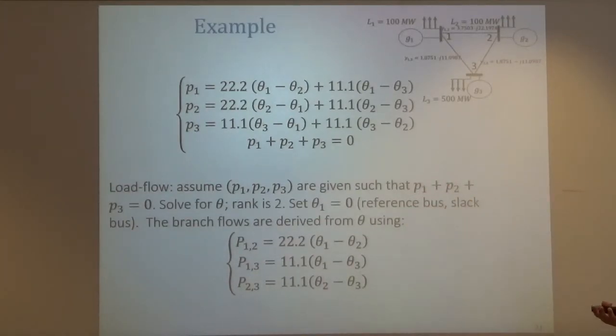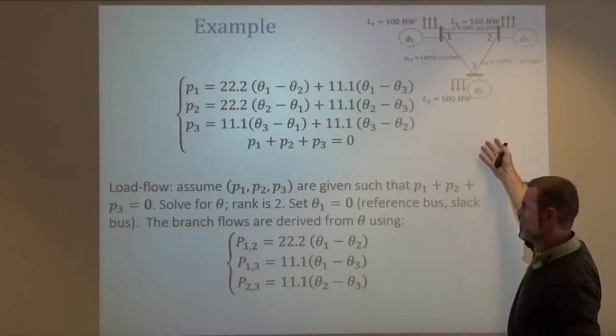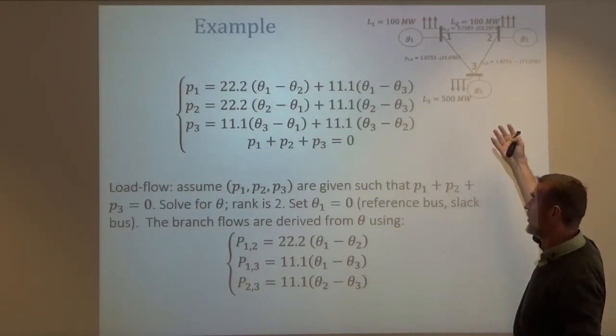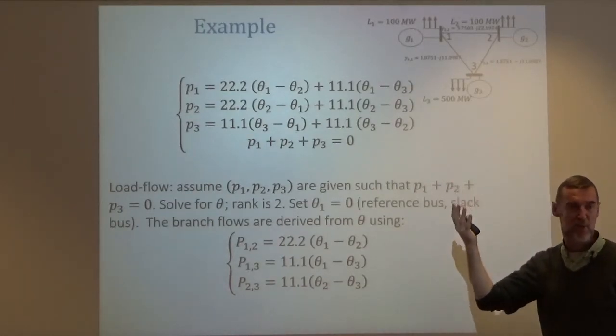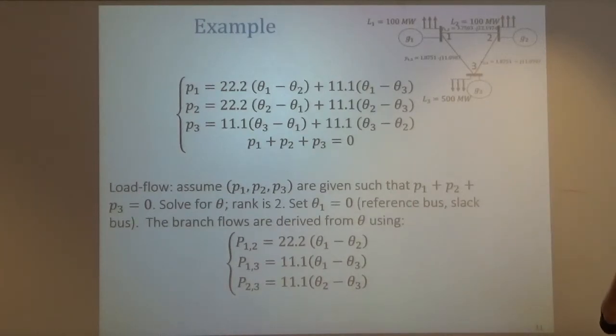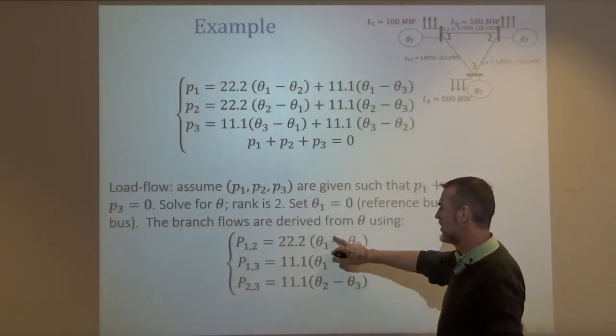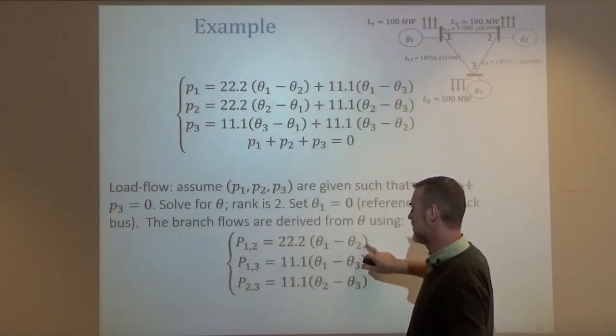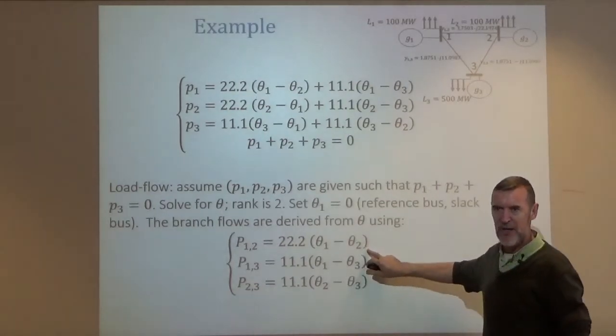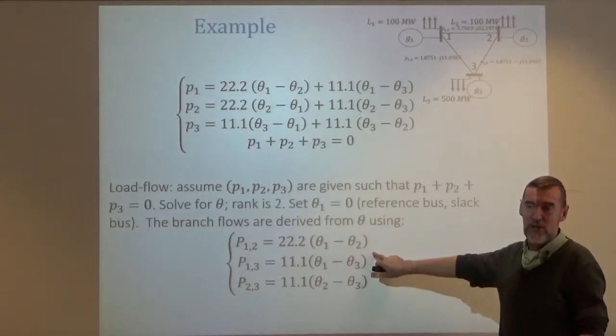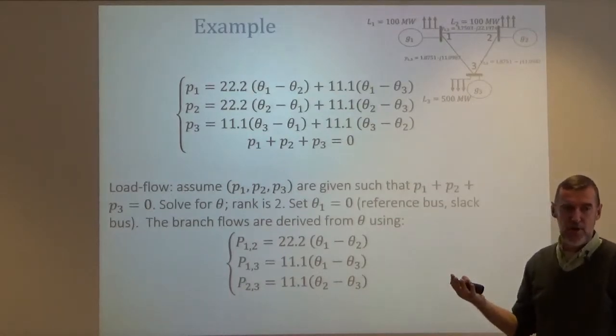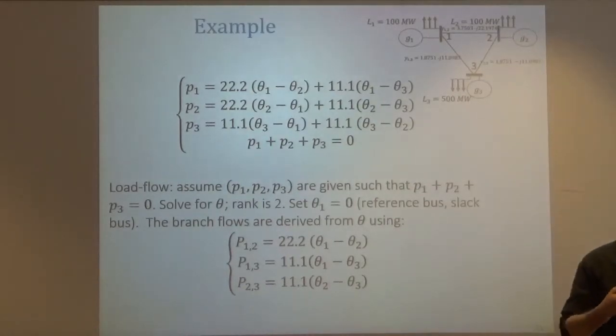In fact, the line currents are ignored in this formulation. If I had the line currents, I could compute the losses. Since I cannot compute the losses, it means I don't have the line currents. This is one of the justifications why people often use the maximum power flow on lines instead of maximum current. But here I can compute the maximum flow of lines using those, so I can express the quantities on the maximum flows of lines. Of course, I cannot express the voltage constraints because I'm assuming all the voltages are equal to 1 in magnitude here.